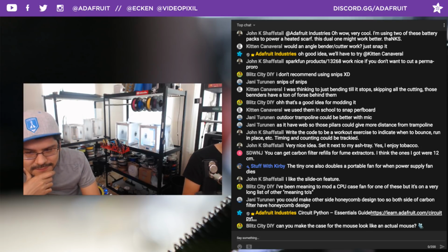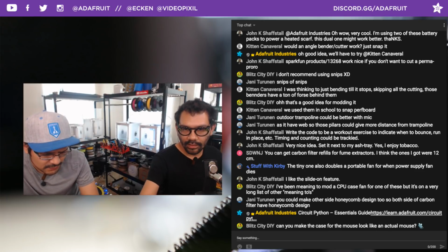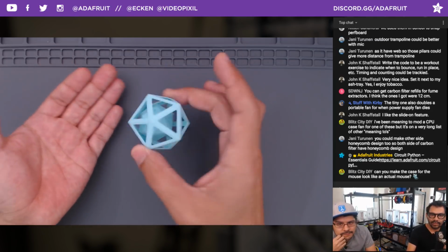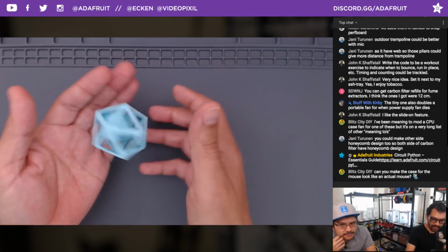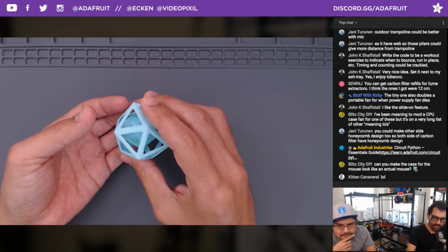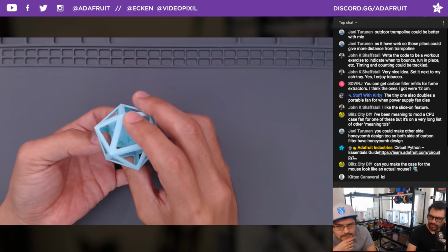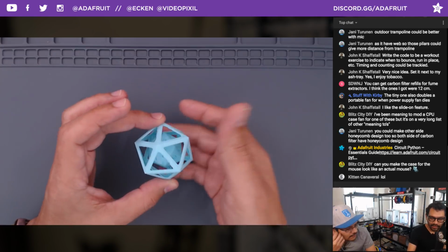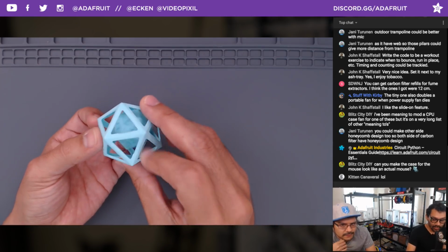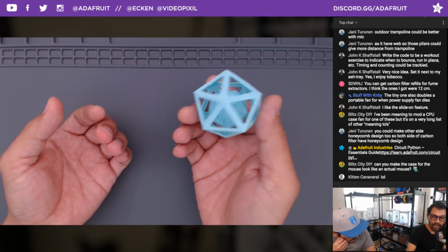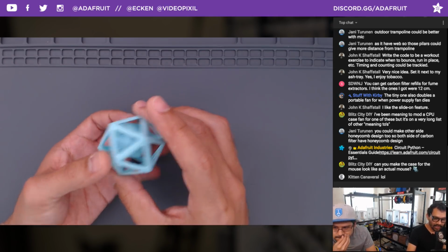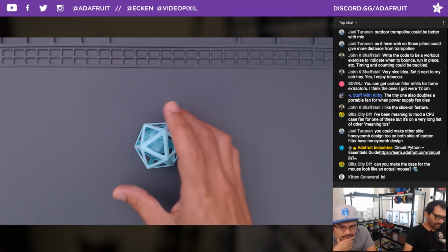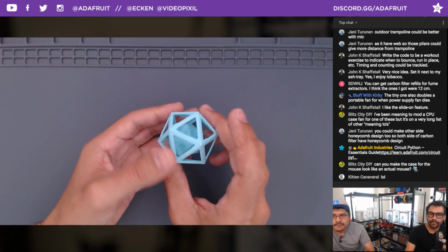Pretty cool. So that's what we're working on, a couple different things. And then, of course, the D20. That'll also be another nice little filler project in between the bigger projects. We printed a smaller one. Yay, it works. We're using the 0.25 millimeter nozzle. I think the 0.4 millimeter should work pretty well for this as well. Again, we just wanted to test the 0.25 to see how the quality was. So you get this really nice 100 microns on this using PVA. We were just testing out the different print cores to see if the calibration on that was really good. And it worked excellent. Sweet.